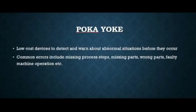The next lean tool is Poka-yoke. Poka-yoke is a low-cost device to detect and warn about abnormal situations before they occur, or once they have occurred, to stop the process. Common errors include missing process steps, missing parts, wrong parts, faulty machine operations, etc.